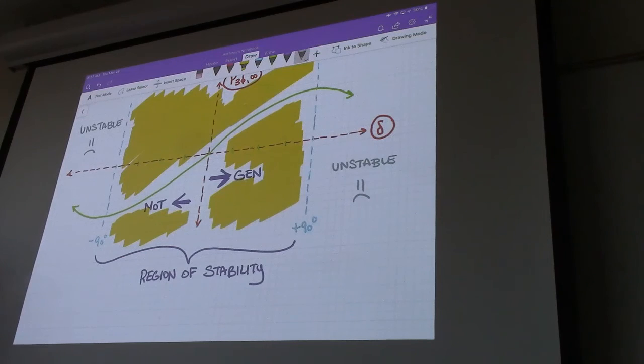Yes. In the beginning of this lecture, you were talking about how this is a blackout. What's the difference between the blackout and the brownout? Well, so a brownout is essentially when we run the system in a stable manner, but at rated values lower than what we normally do. So it's essentially voltage droop and lowered current maximum from the plugs. So everything's stable, but you're not getting 120, you're getting 110 or 105, and the maximum current that you can draw, well, I guess that's predominantly set by the breaker, so that probably wouldn't change. But it's like your car is still running, but you're stuck in like first gear or second gear. Whereas instability is like your engine's exploded.